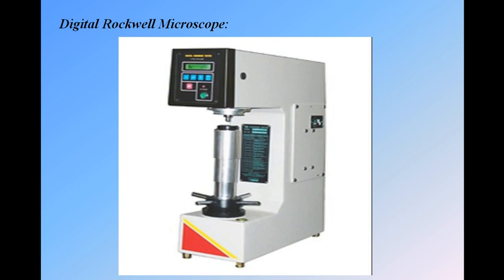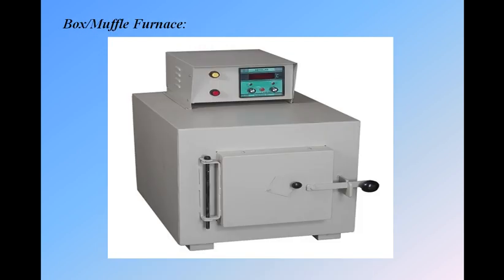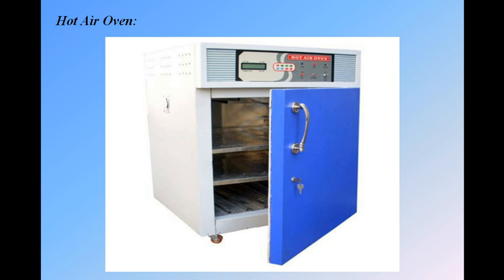Okay, next, this is the box or muffle furnace. This is a furnace which can be used for heating any component up to 1200 degrees Celsius. 1200 Celsius means it is below the melting point of cast iron and steel. So in this we can heat any material up to 1200 degrees Celsius and see what changes it has inside. Okay, next, this is a hot air oven.